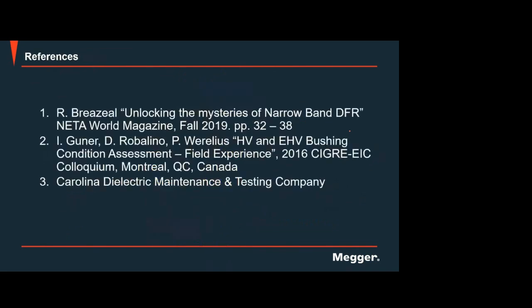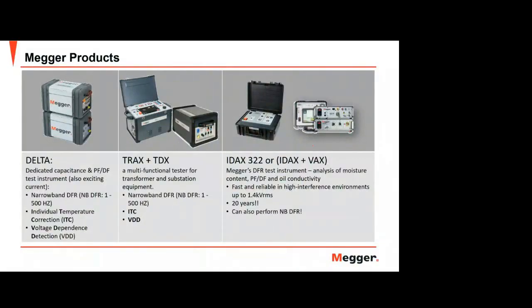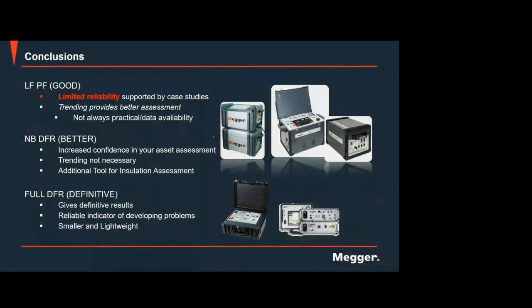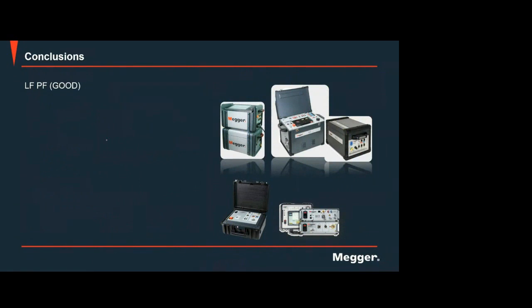The first difference is that you have a smaller equipment here, and this one is bigger, right? That is the first difference. But why is it comparable? Because normally, if you do insulation power factor, insulation assessment or insulation testing, we treat the insulation as capacitance. So we are getting the IC, the capacitive current, for the insulation, okay?